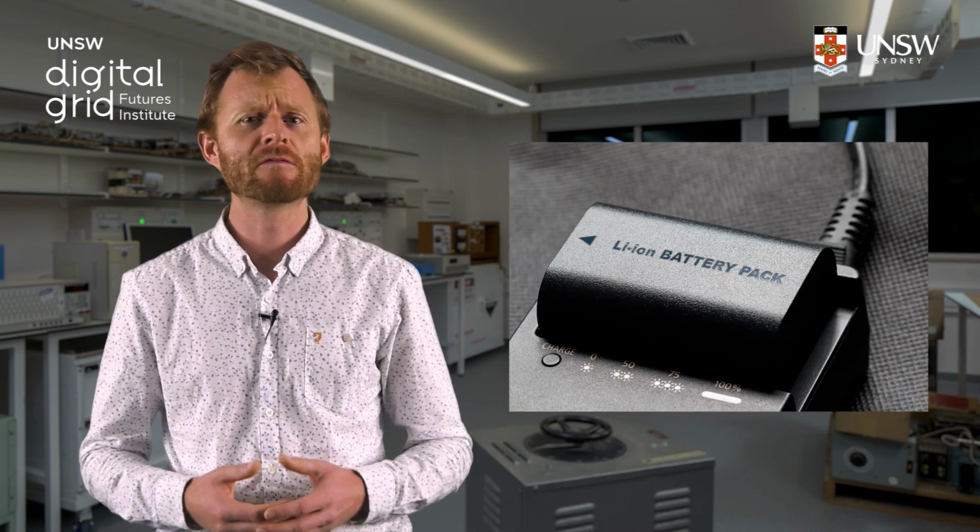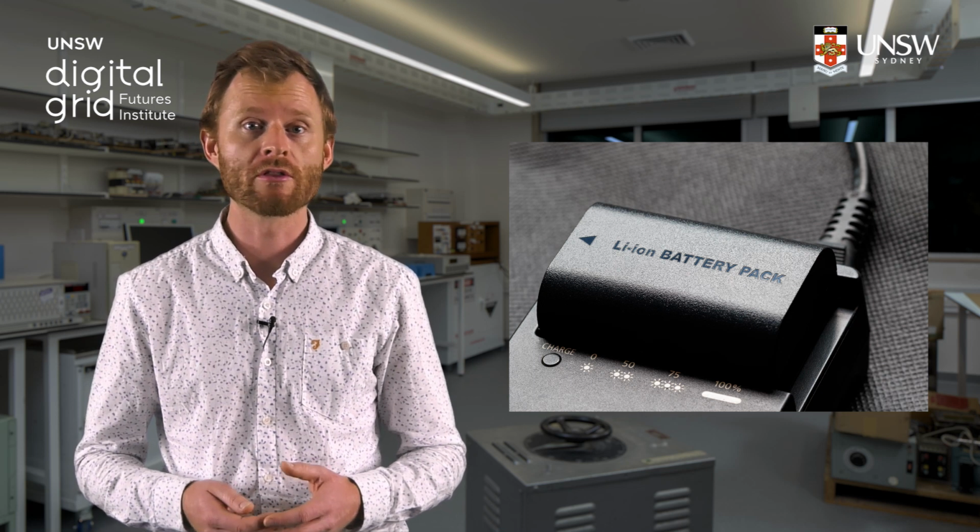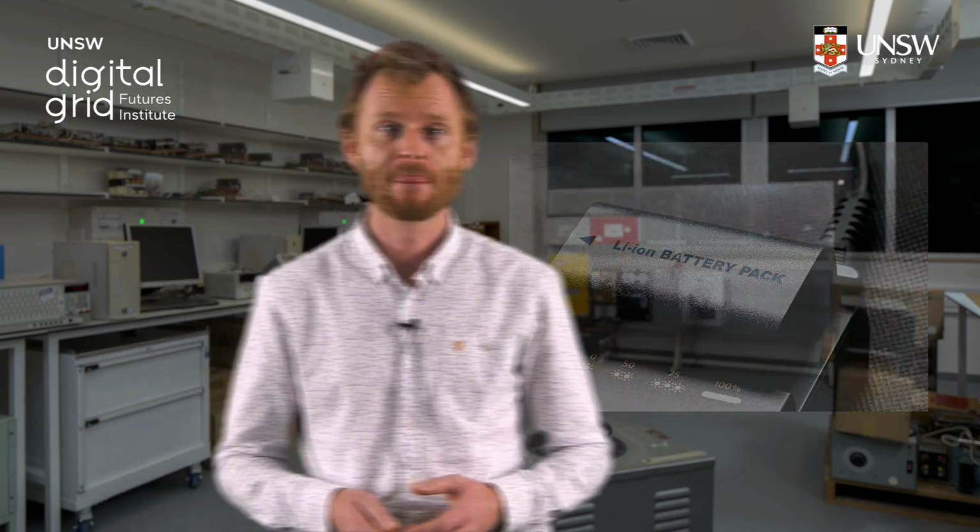And as we charge and discharge the battery, we generate heat, especially if we charge and discharge the cell very fast. If the cell overheats, this can lead to thermal runaway and potentially end in a battery fire. Therefore, it is very important that we regulate charging and discharging to ensure that the battery does not overheat. This is one of the jobs of the Battery Management System, or BMS for short. We will discuss the BMS in depth later in this course.